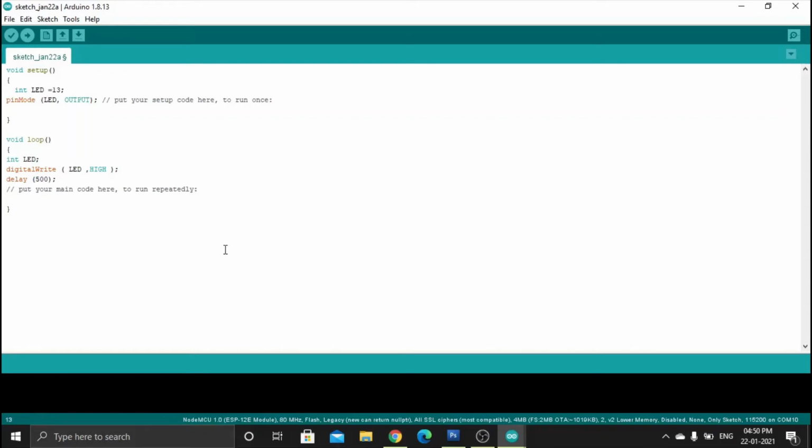and again I'm gonna turn off this same LED. So for that it is the same coding, like let's say digitalWrite, LED, LOW. Here I'm going to turn off this LED. You can see I'm using all caps, and for the control thing I'm using digitalWrite, which will be understood by this IDE. So now I have turned it off, but I need to hold this off position for a certain period of time. So I'm again writing this delay for 500 milliseconds.